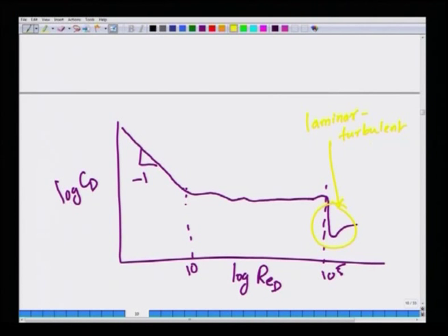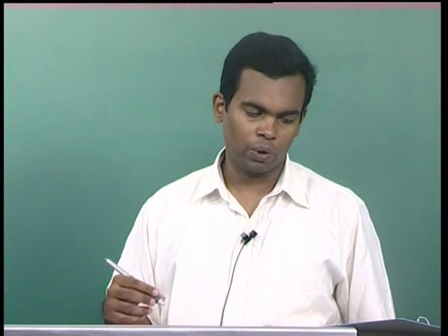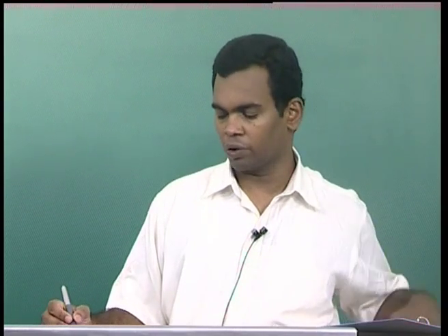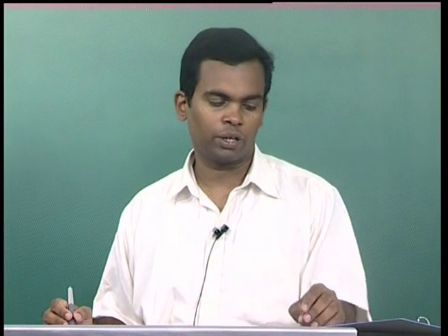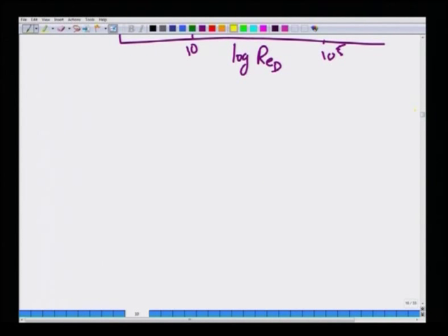As in any flow, when the Reynolds number increases, many flows are susceptible to this transition from laminar to turbulent flow. So, this also does that. What is interesting is you find a sudden decrease in the drag coefficient that marks the transition from laminar to turbulent flow, and that is because the separation in a turbulent flow is delayed compared to laminar flow.